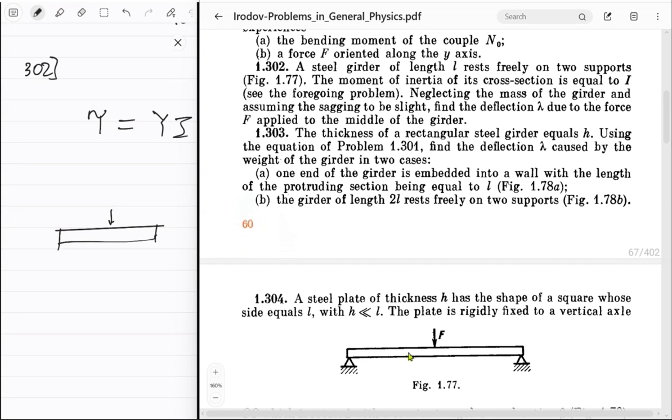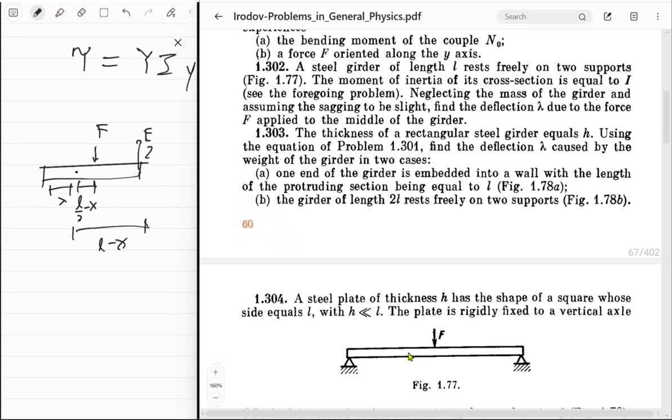So this is our force in this direction. We got this as x. This is just equal to L upon 2 minus x. This thing is equal to L upon 2. Now it's complete combined is L upon 2 plus x, right? So from here to here it's L upon 2 plus x. Oh no, sorry, it's L minus x. Sorry for that. And over here you got F upon 2. So the torque is how much? We only care about the magnitude anyway, right?